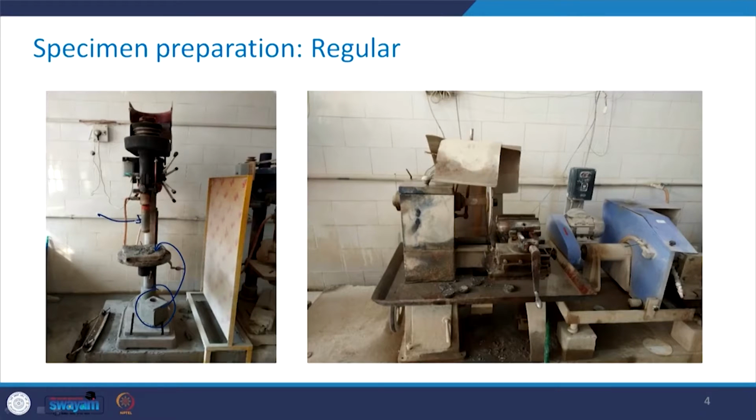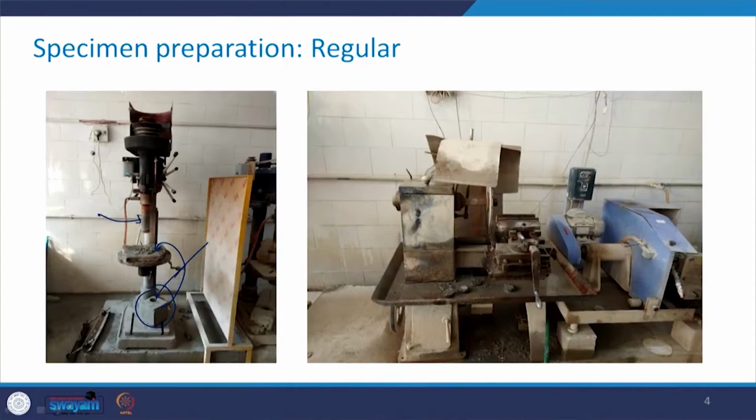Okay, so with the help of the motor which is mounted here, the whole assembly is brought down, and because this bit is of a very hard material like a diamond drill bit, it goes inside the rock. So you can see here one hole. So one sample has been taken out from this particular block. So this drill bit goes inside this block and drills it, and then a core can be retrieved by this procedure.